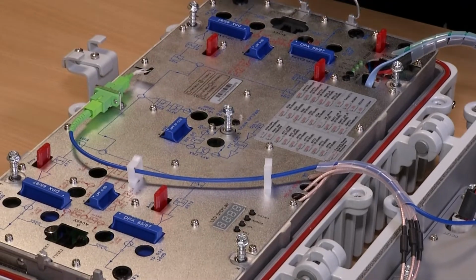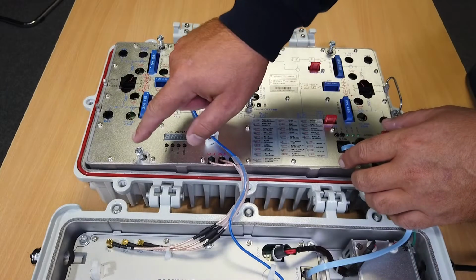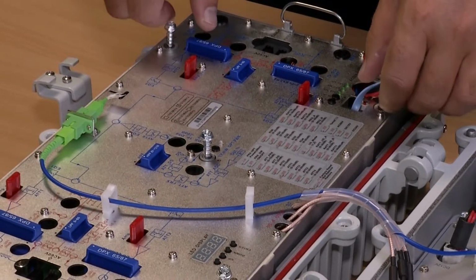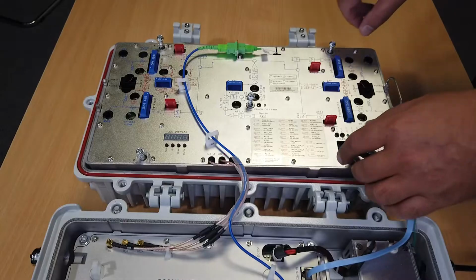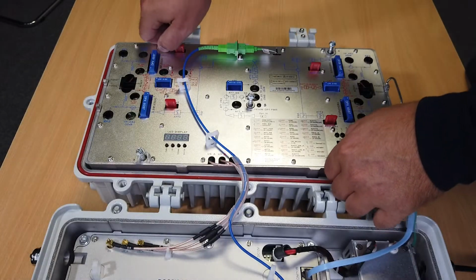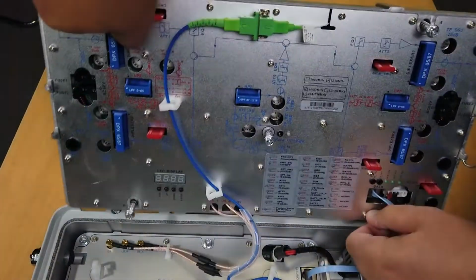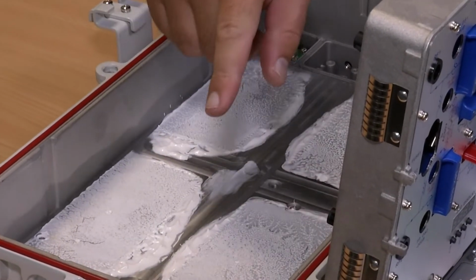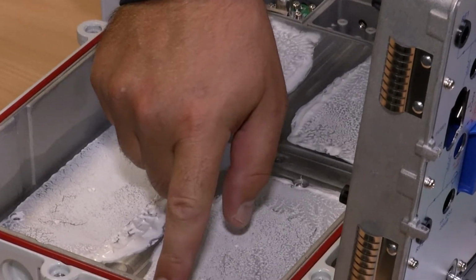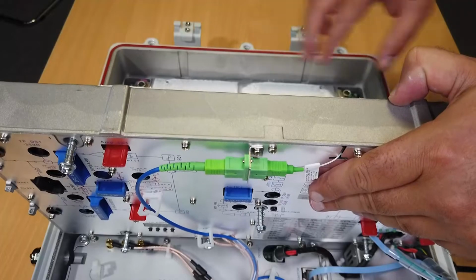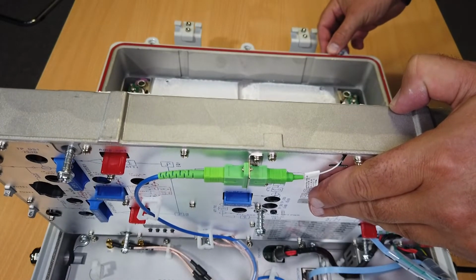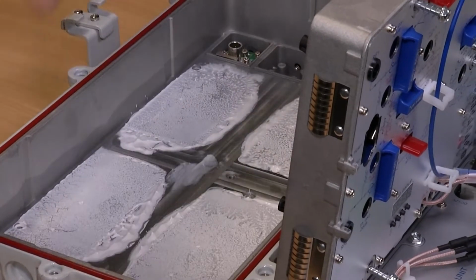If the TV module develops a fault, then just remove 5 screws to change it easily with the device still operating. Just unscrew and remove. It's important to note that all the connectors of so-called armatures stay in place, so you don't need to do any changeovers. The TV module connects to the baseboard via a single plug.